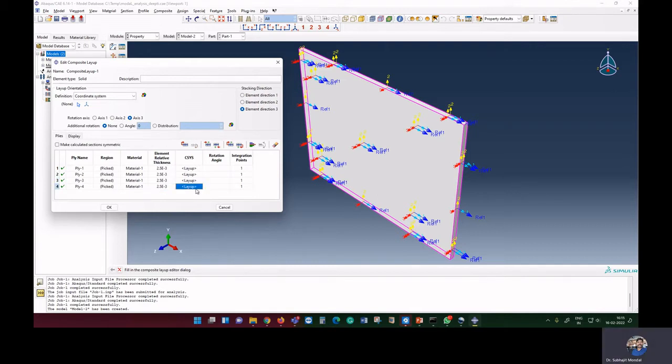So now you can see we have a total of 10 mm thickness. Now here it is asking for the CSYS for each layer. For each layer, CSYS, basically a datum point, they are asking. So here we can select datum for all. Okay, so here you can see by default it is selecting like this. Okay, it's fine. Now here it is asking the angle of orientation.